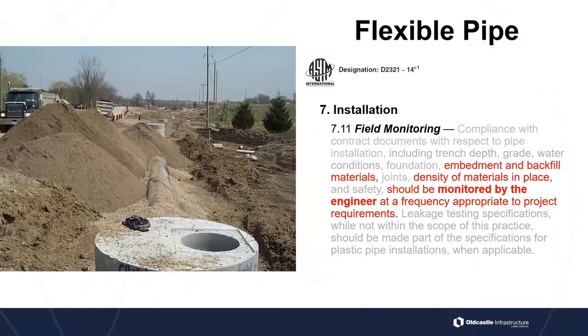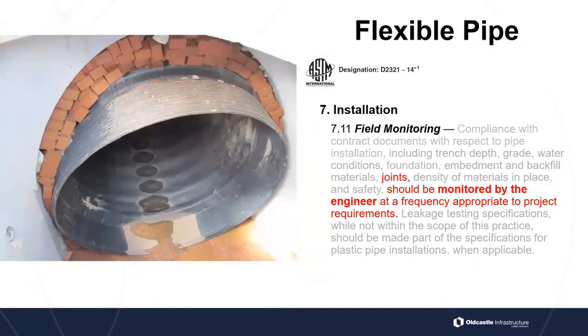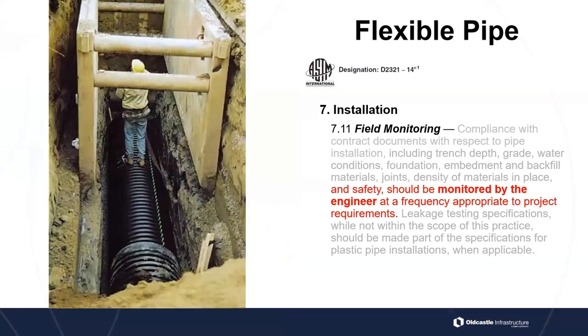What about joints? Are the joints correct? That looks like a pretty interesting and unique way to grout in a joint there. Does that meet the specs? It sure doesn't look like it. When we talk about safety, is that a safe use of that trench box? Hard to say there. Doesn't look like it to me, but that's up to you as the engineer to determine.